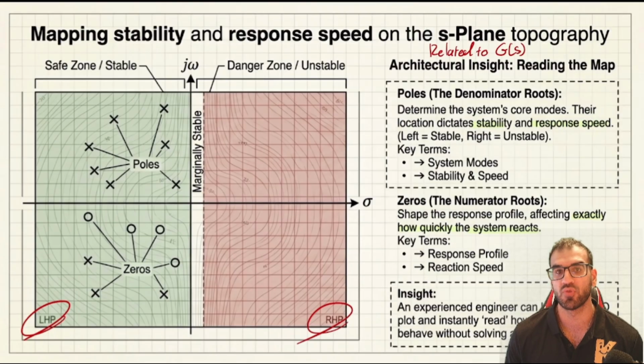On the other hand, we have something we call zeros. Zeros mean at what point your system is going to be 0. So by putting the numerator equal to 0, we can find some numbers. By having those poles and zeros, we can completely understand what would happen when t reaches infinity, what would happen as a steady state situation, and whether my system is stable or not.